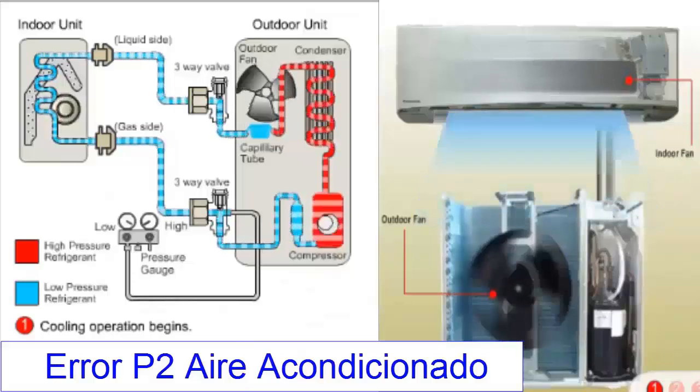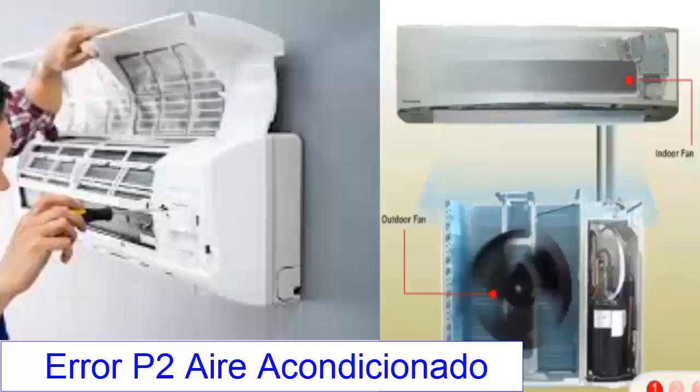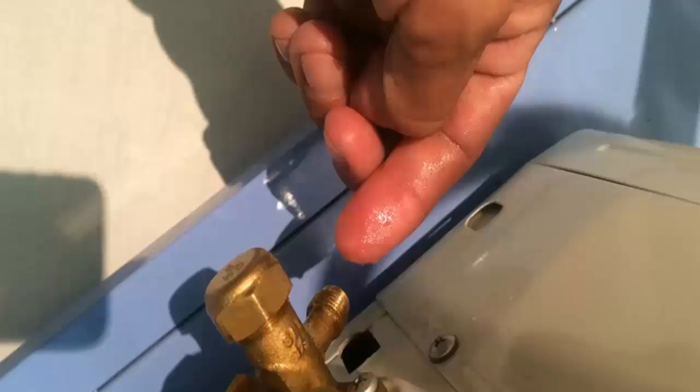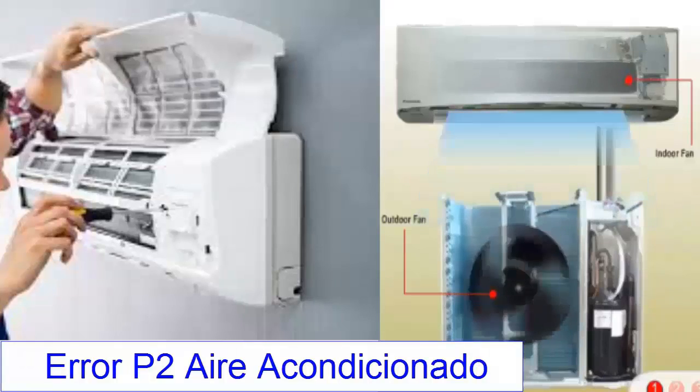8. If there is refrigerant oil at the junction, apply soapy water or a leak detector to check for any leaks in the system. 9. If you find any leaks, repair the leak, then vacuum and recharge the refrigerant. If the refrigeration system is blocked, replace the high-pressure valve.